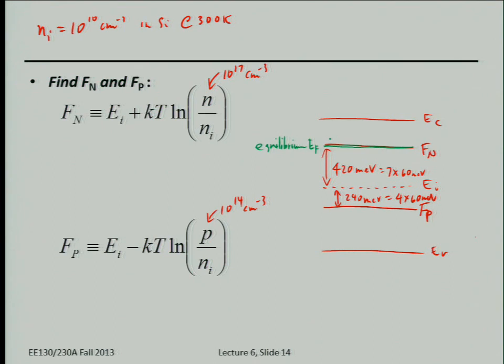Great, np does not equal ni squared. That's actually correct. So basically, thermal equilibrium means that your electron and hole concentrations are just determined by thermal energy. Depending on the temperature, you're going to have, on average, some concentration of electrons and holes. That's what thermal equilibrium means, that electrons and holes only exist because of thermal energy. And if you dope it, yes, you'll tend to favor electrons more than holes, like for n-type doping.